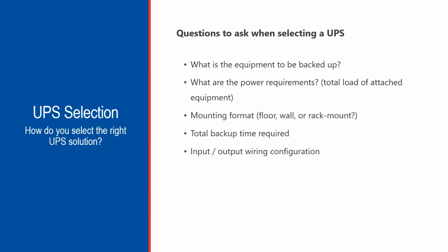What's the total backup time required? This will be determined either by the user or by local regulations in the case of vital systems, such as fire alarms and emergency communications. At the end of the day, understanding the need versus the want is important. I think sometimes people can get a little bit of sticker shock when they ask for 24-hour runtimes, when in reality they really only need 4, 6. But when you understand the application, you'll understand the total backup time that's required. But more importantly, understanding the total backup time needed will help you select, again, the right UPS.